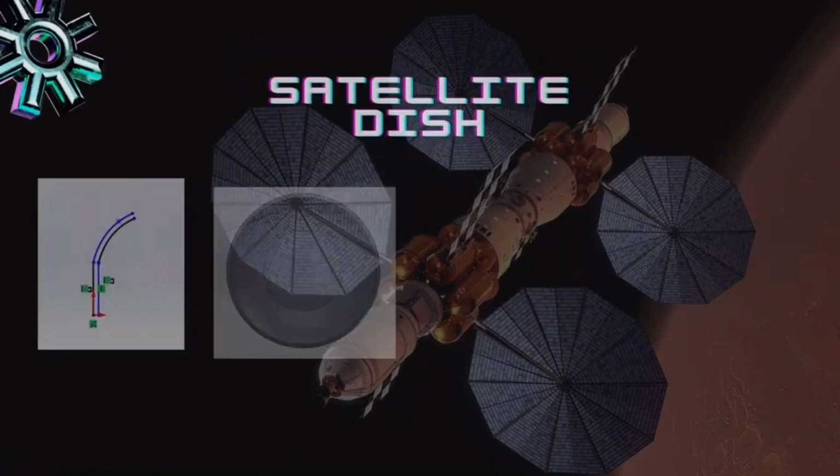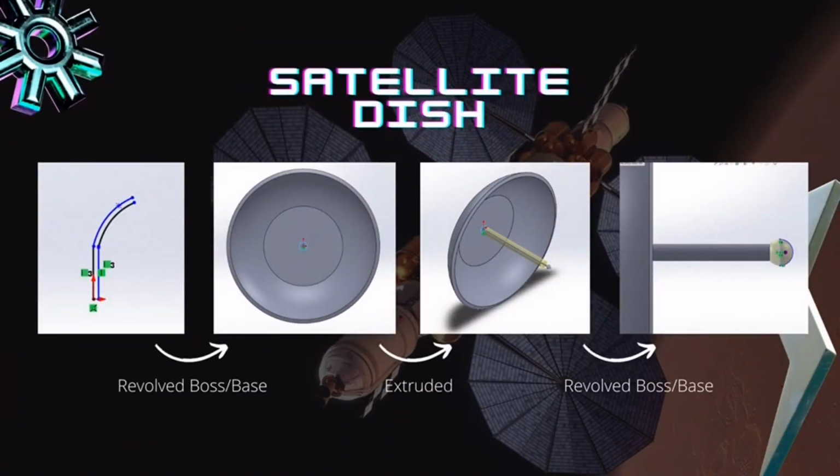feature mode. The satellite dish is the tool for receiving any signals or information around the Mars Base Camp. In sketch mode, we create a straight line first, then use the spline tool to create the curved line. When it looks good enough, use the offset tool and Thick Reverse so that it will offset inside. After joining all the lines together, we'll get the surface. Then revolve it about the horizontal line at the bottom for 360 degrees.